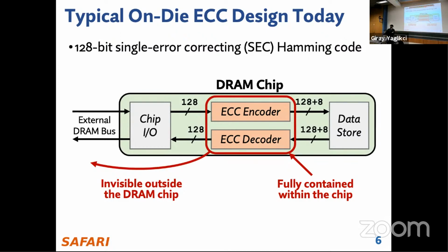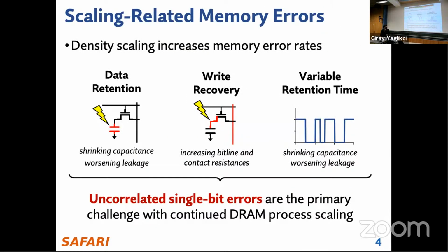So, yeah. It's at risk of what? Just like a bit flip, right? Going from 0 to 1, 1 to 0. So no, it's not attacked by RowHammer or anything. It's just naturally flipping. Yeah, that's fair. I was talking in the beginning slide about these scaling-related memory errors, right? So these are, I guess you could say, naturally happening. You could exacerbate these through malicious activity. Like, if we crank up the temperature, these become more common and so forth.